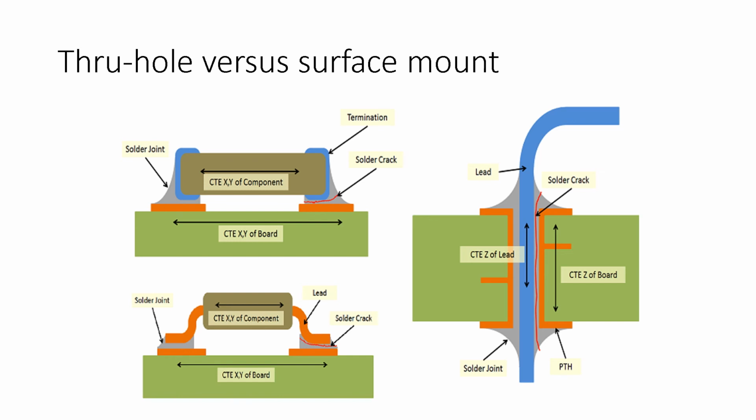And the leads, or the legs of the circuit in that regard, are usually actually bent with a tool to make sure that they have very, very specific angles of bending, because that's going to relieve some of the stresses on that component. The worst thing that you could have is something going through a lot of thermal cycles, expanding, contracting, and then a lead breaks off, or a leg of that breaks off, and then that would lead that entire circuit potentially to disarray. So that's something we want to look at too.